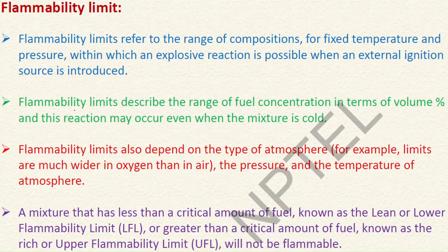Now coming on to the flammability limit. The flammability limit refers to the range of compositions for fixed temperature and pressure. It is the composition of the mixture of fuel and air at a definite temperature and pressure within which an explosive reaction is possible.